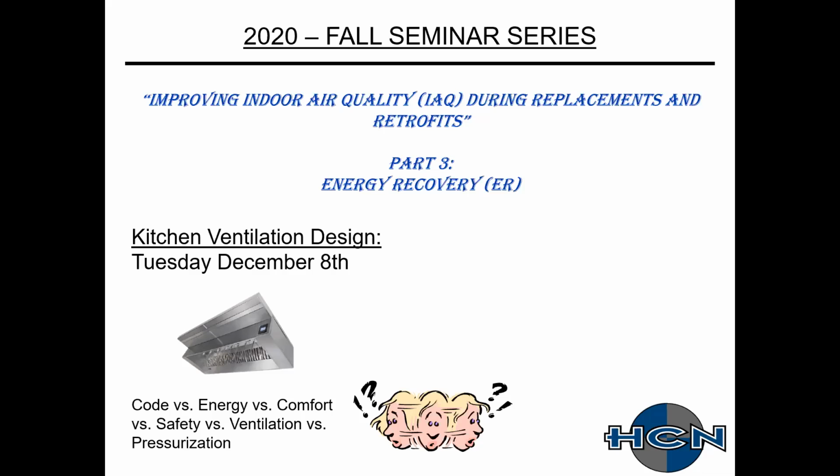There's a lot of requirements for safety in terms of exhaust and fire protection, ventilation requirements, and then also you have to be concerned about pressurization for keeping smells to a minimum as they travel, and then also you don't want bugs and other things coming in from the outside entering into your kitchen where you're preparing the food.